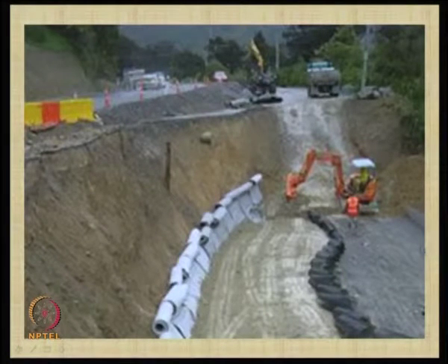Water comes here, and that should not create a shear failure here. So all the water should go through these prefabricated vertical drains. This is another application, not a consolidation type: PVDs have been used behind retaining walls also, to increase the rate of drainage.